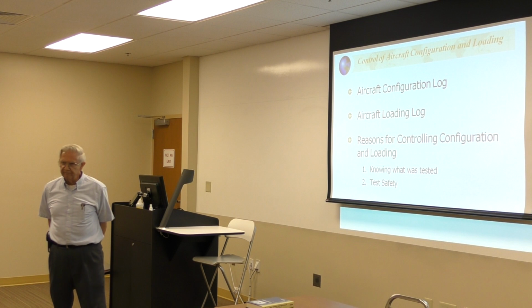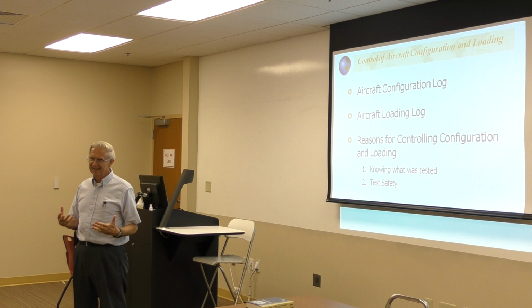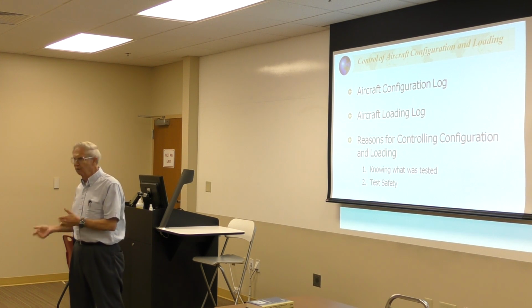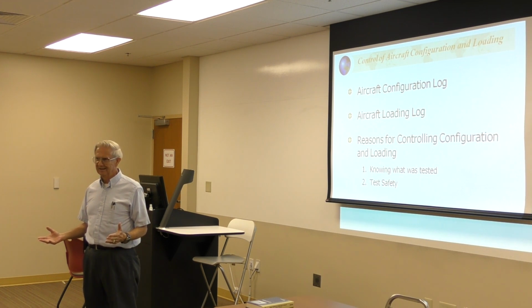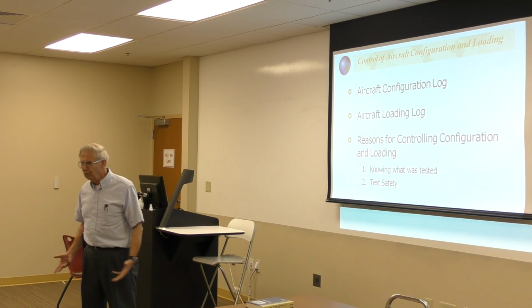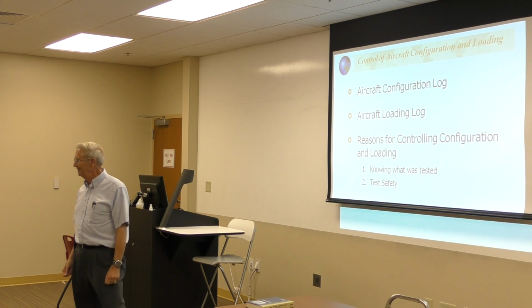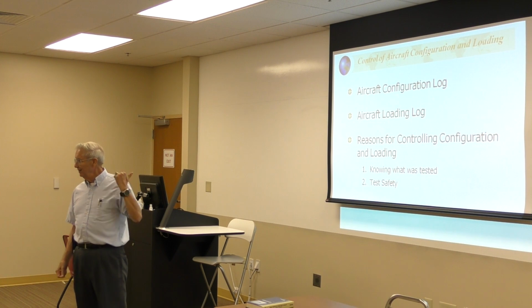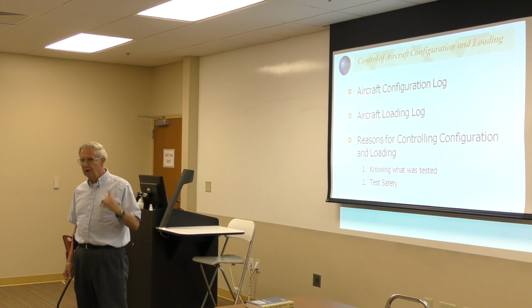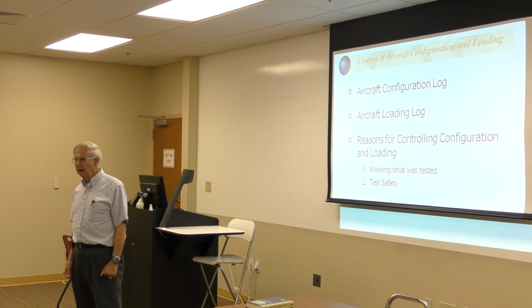Because what will happen in a flight test is this. You'll be busy doing things. You'll be collecting data. When the weather's good, you're going to fly. Okay? And then when the weather's bad, you're going to reduce data. Trouble is, if you haven't identified that data with what the configuration and loading was, when you get ready to reduce it, you won't remember.